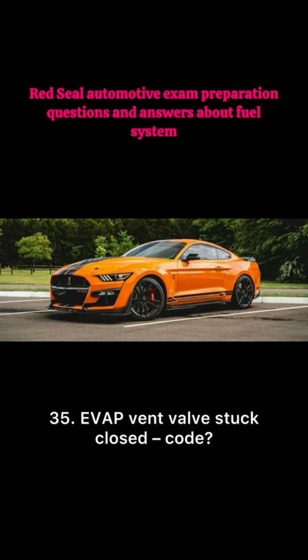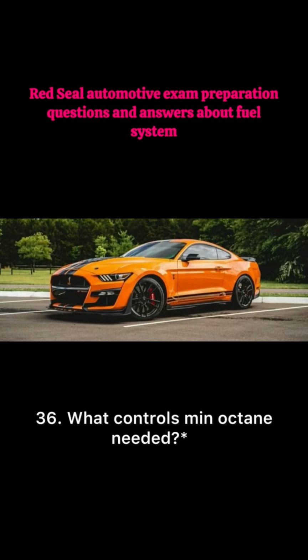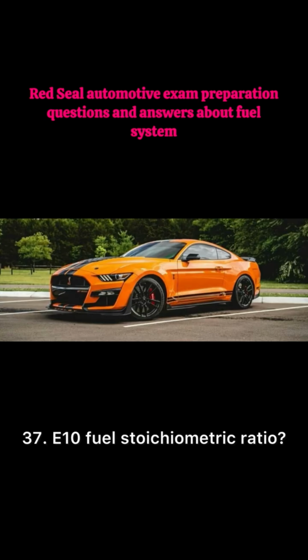35. EVAP vent valve stuck closed code. P0446. 36. What controls min octane needed? Compression, timing, knock control. 37. E10 fuel stoichiometric ratio. About 14.1:1, needs more fuel.